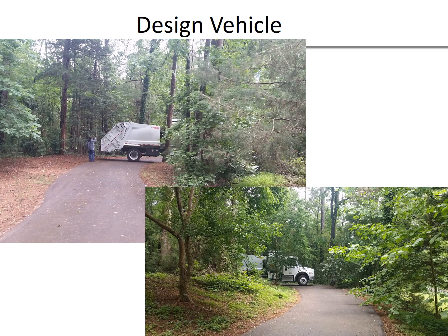Sight distance, so thinking about the eye height and braking distance, which vary between passenger cars and trucks. Acceleration and deceleration are going to have an impact, particularly your traffic signals, intersections, and vehicle stability. So certain vehicles with higher centers of gravity may be more prone to skidding or overturning, which can affect the design speed and superelevation design components.